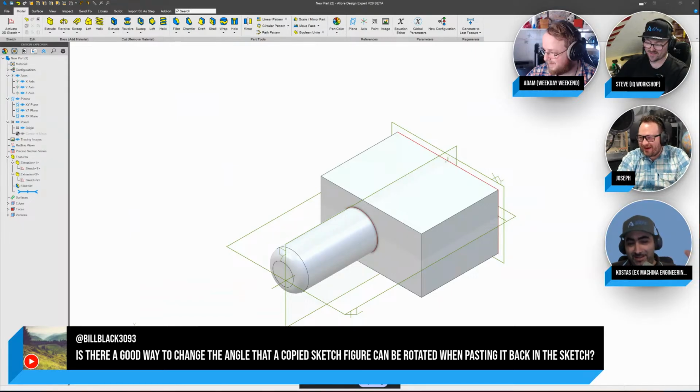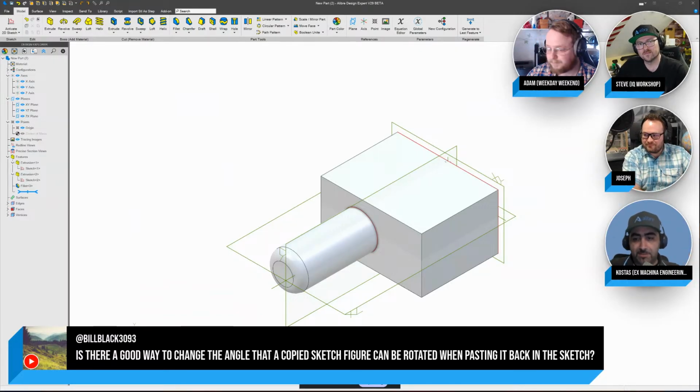What you need to know there, Bill, is tacos are nice. After that, you need to know that when you're using the paste stamper, when you copy with a base point, then you can use a paste stamper. And when you stamp what you copied, you also stamp the constraints and dimensions. So if you have an angle dimension there, you can stamp it, and then you can change those. For example, you're copying a square and you're picking up the dimensions as well, and you stamp it, and then you can change those dimensions and make a different square. That's a really powerful use of the paste stamper, right? And you can do all sorts of stuff with that.